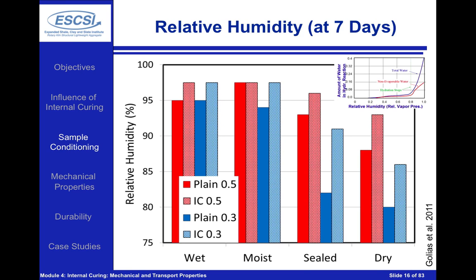So now if we look at different concretes that are cured in different ways and we measure the relative humidity inside of these systems, effectively what we're doing is we're measuring the size of the pores that have been emptied under these different conditions.